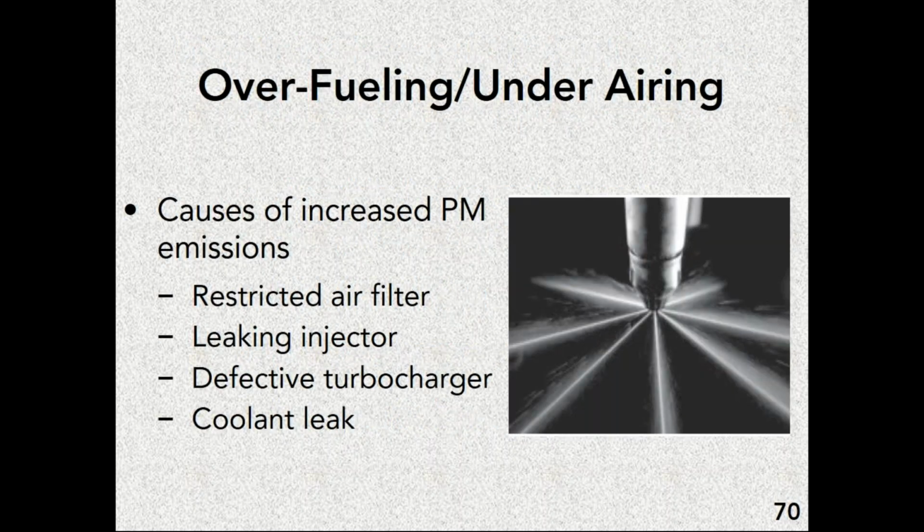Beyond modifying the engine's original equipment system, you also need to pay attention to how the system is functioning. So for overfueling or under airing, I don't know if I can say this enough, but unburnt fuel equals particulate matter. I think I said that early on. I'll say it again. Unburnt fuel equals particulate matter. Where do we get unburnt fuel?